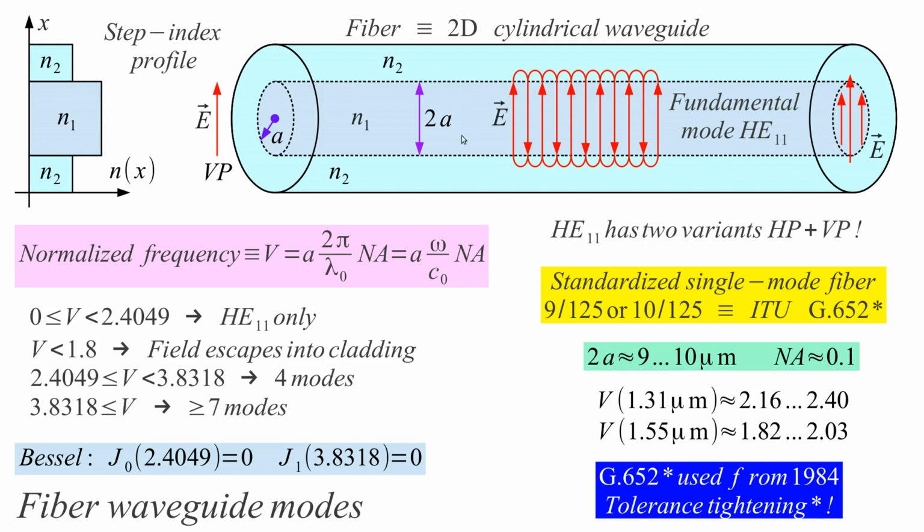And this very thin core, and further it also has much lower numerical aperture. The numerical aperture is twice smaller than the multimode fiber, and this means just 1/4 of the coupled light. So if we have a 10 milliwatt LED coupled to a step index profile single mode fiber, the coupling efficiency is 0.1%.